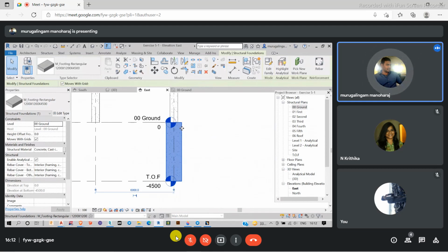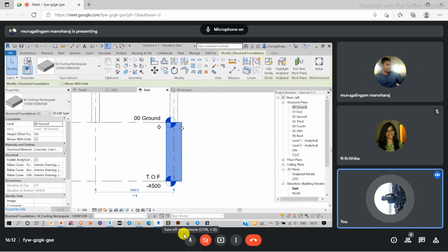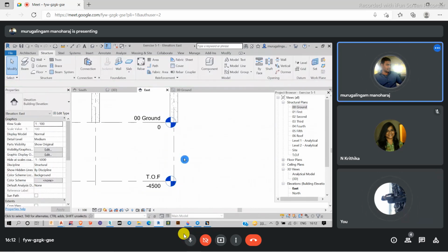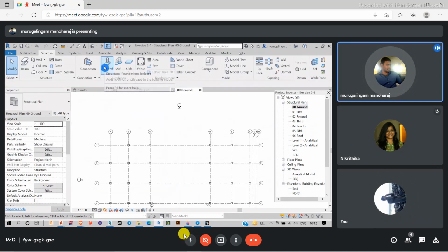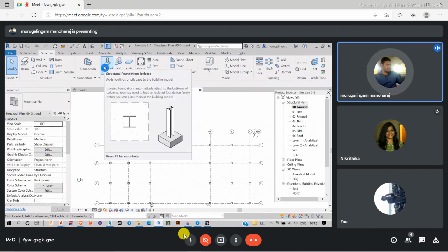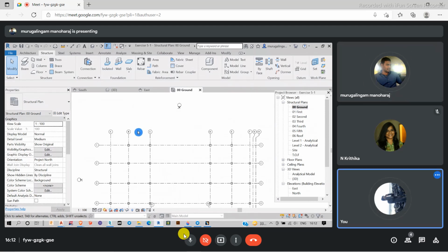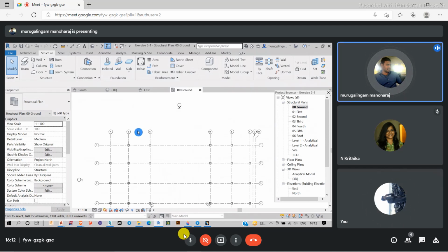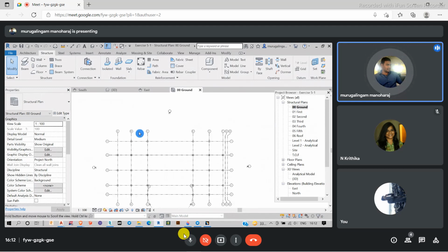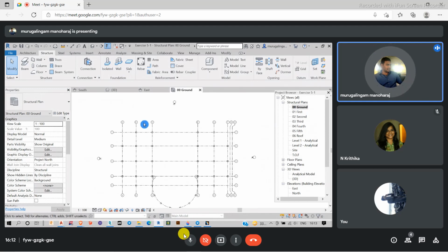Are you able to get this point, Aman? No, sir. Sir, can you please repeat it here because I'm getting confused. Okay, once again, I'm repeating. See, the thing is that I don't have a pile kind of system. Piles are a type of foundation which we put when the soil is loose soil. Suppose when I am digging for a foundation, I am finding only loose soils. So I have to go deeper to reach the hard soil. So it is not possible for me to put the normal foundation at that level.